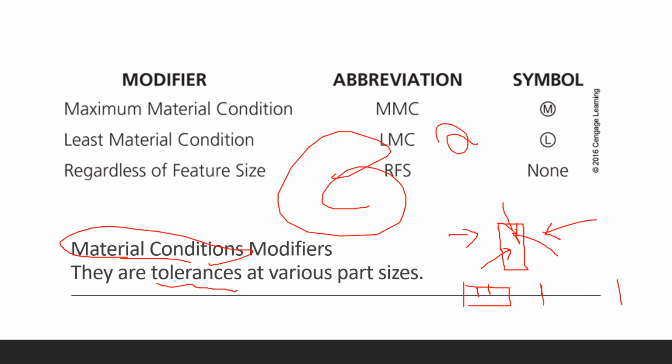When it's hot, the material expansion is going to be varying. So if you have a measurement from here to here that is one value, when the part is subjected to extreme temperature or something, then you're going to have variations. Whatever the variation is, these parts got to be within the tolerances, right? Considering all environmental factors with that part feature and also the material condition.